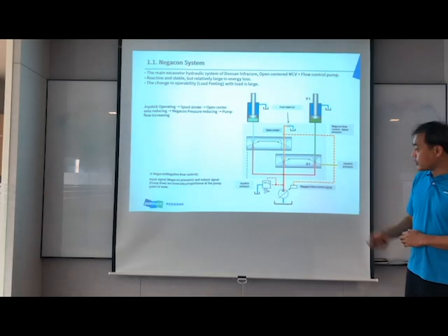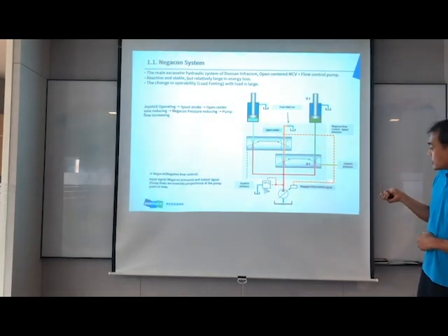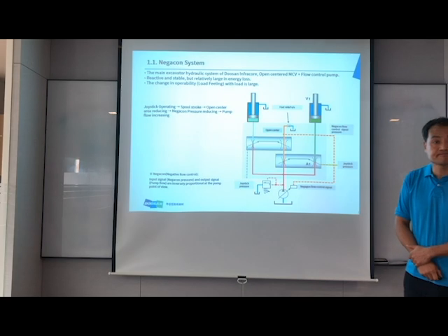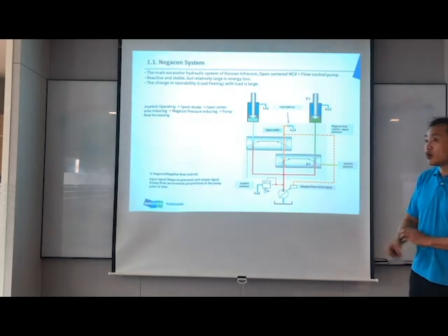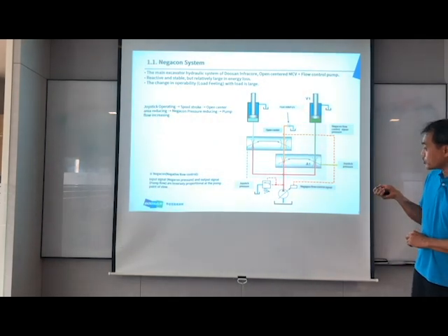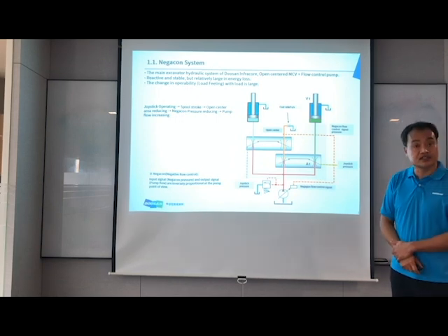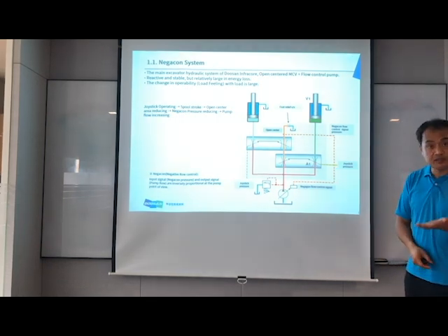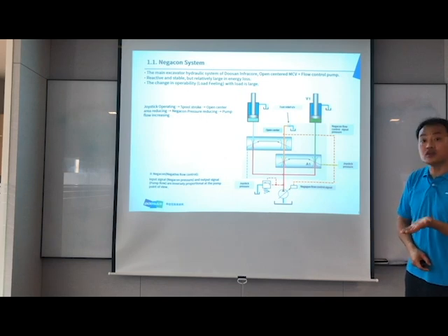The flow depends on this dotted line pressure. For example, when the machine operator moves the joystick, the spool shifts and the pressure goes down. At that time, the pump recognizes the spool shifting, right? At that time, the pump makes more flow.